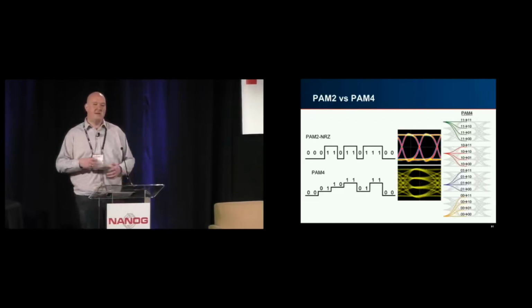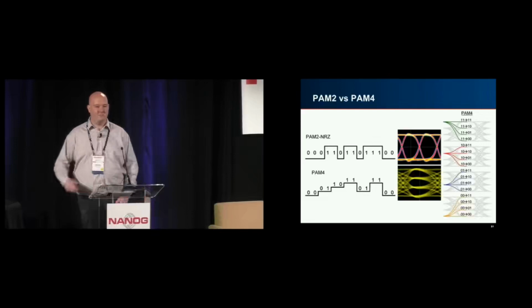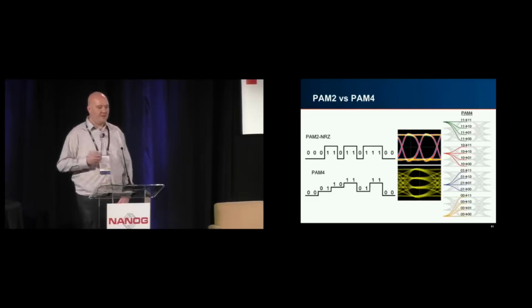So you can have lower power systems that are cheaper and that integrate into pluggables. In fact, this is very likely to be one of the bases of 400 gig technology, which is going to need this type of technology. And today there are vendors shipping 100 gig DWDM tuned pluggables that use this technology. So this is what's happening here. You're introducing these four levels of state, and you're able to encode 2 bits of information per symbol change.